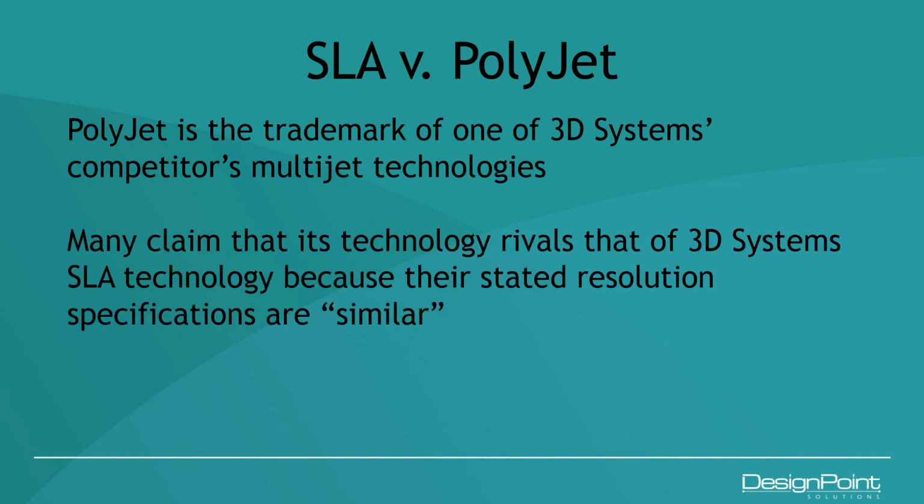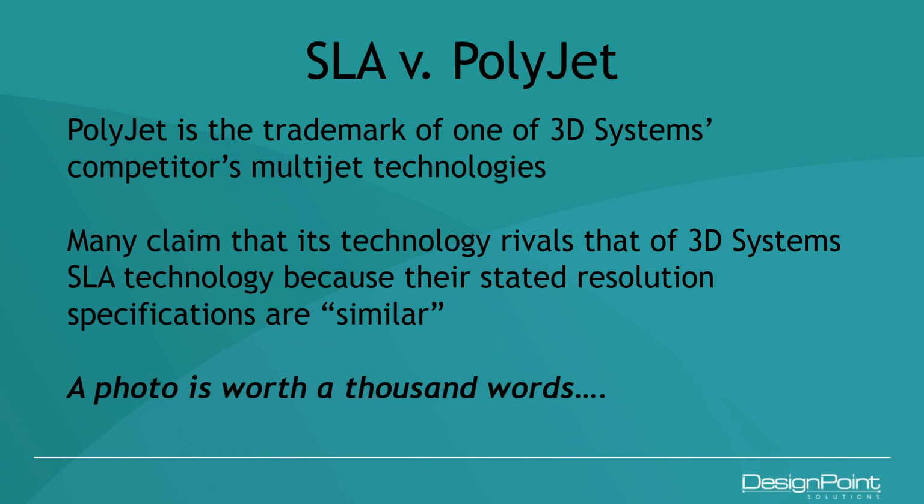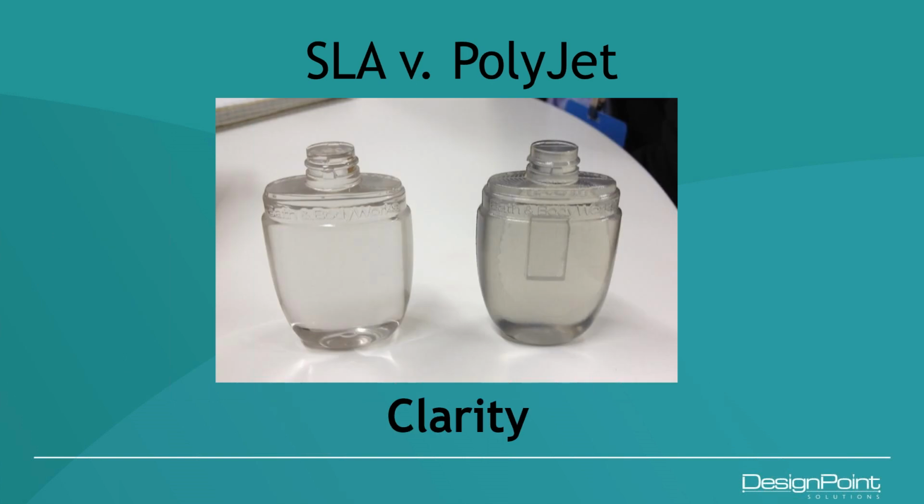Many claim that the PolyJet technology rivals that of the 3D Systems SLA technology because their stated resolution specifications are similar. We say that our resolution's about 1/1000th of an inch in all 3 dimensions, and PolyJet says, well, yep, they are as well, about 1/1000th of an inch in all 3 dimensions. But a photo is worth 1,000 words, so I have some examples I can show you here.